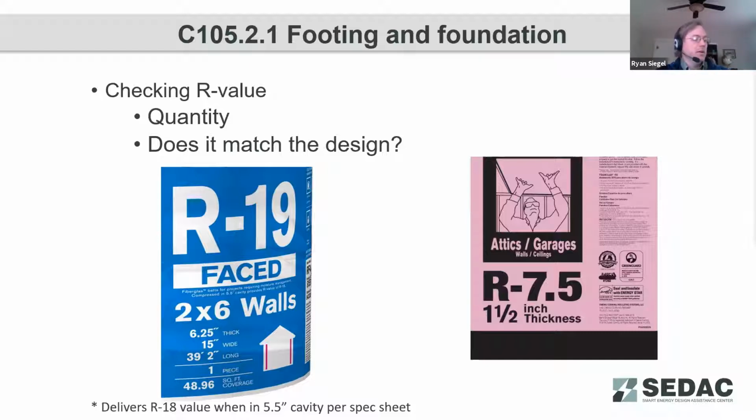May not be substantial for your project, or it could be rather dramatic. If it called for an R19 and you put this in a regular 2x6 wall cavity, then you're not meeting what was called for in the design. So what you'd probably end up having to do in that case, if you needed the full R19, is for a new wall, you're going to have to fur that 5½ inch stud out an extra 3/4 inch, in order to fit it all.